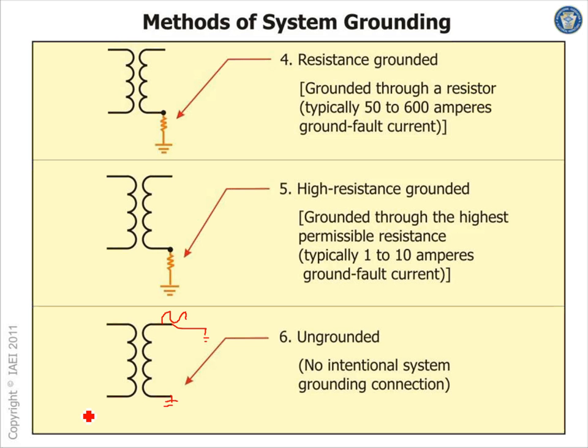If you ground the system, you kill the advantage of the ungrounded system, which is the survivability of the system upon a ground fault. And I hate to say it because it's hard to believe, but studies say 85% of your faults are ground faults. Now imagine if you have a system that can eliminate the interruption of your power system. 85% of any interruption that happens in your power system is eliminated by ungrounding the system. Isn't that great? So if you have a ground fault, which is 85% of your faults, you can basically get rid of all of these.